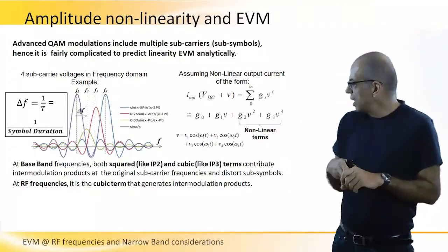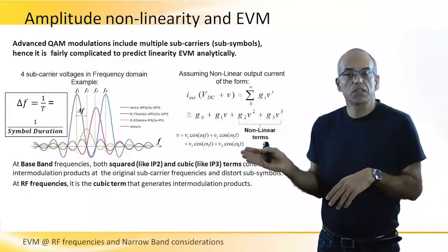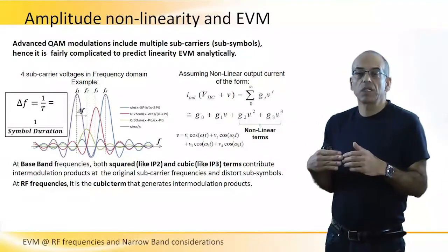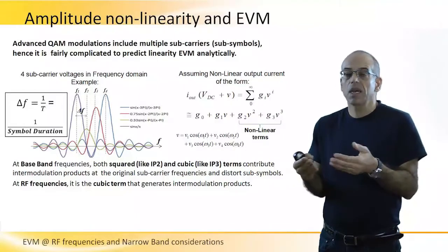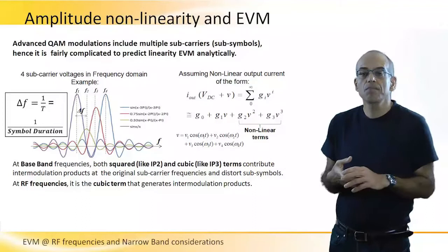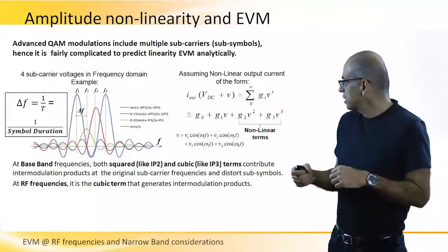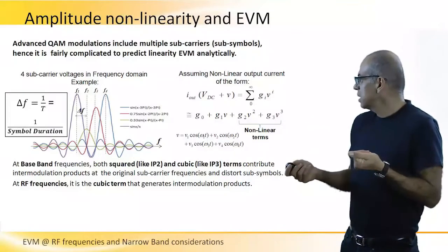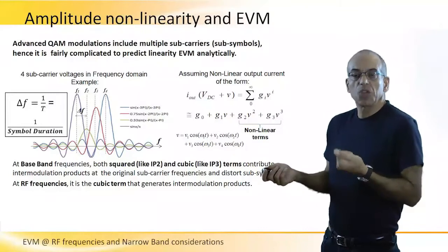It's very nice. However, when we introduce these 4 subcarriers into a non-linear device, such as a mixer or even an input LNA, or if in the transmit channel we introduce these subcarriers to the PA that has finite linearity, then the non-linearity of the device can be described as a Taylor expansion of the output current.